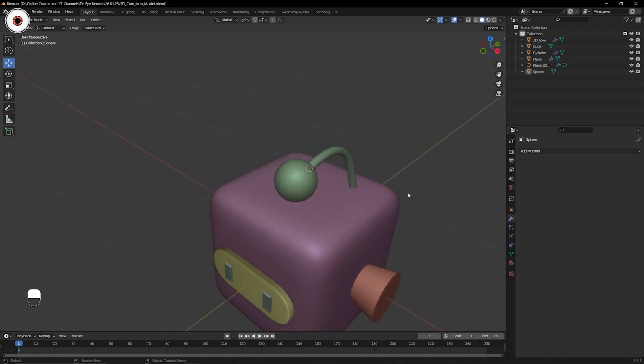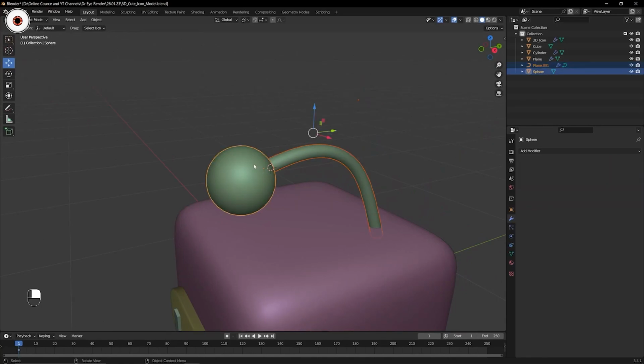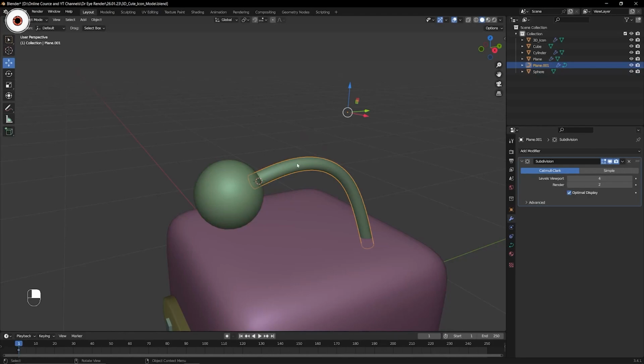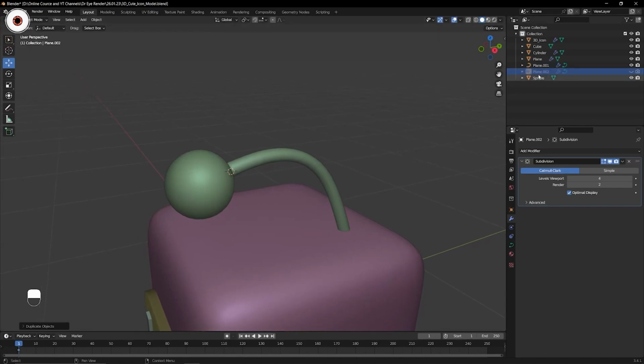You can mirror these two objects separately, or you can select both and press Ctrl J, but you cannot join those because the warning message came, as this is a mesh and this is a curve. So I prefer to convert this into a mesh. But for now we can Shift D and unhide, so it is for backup.